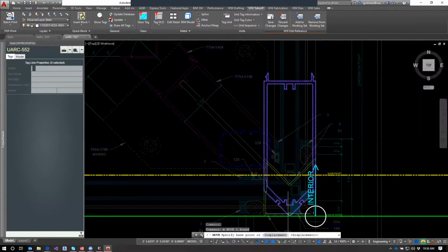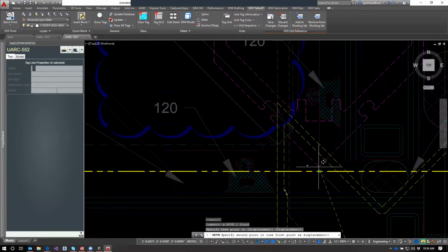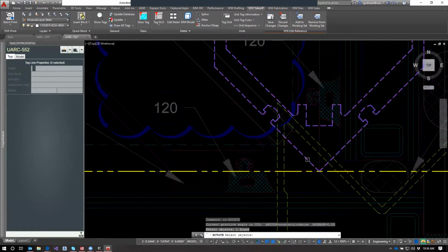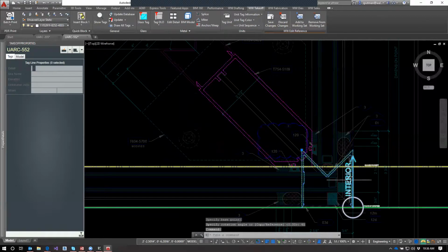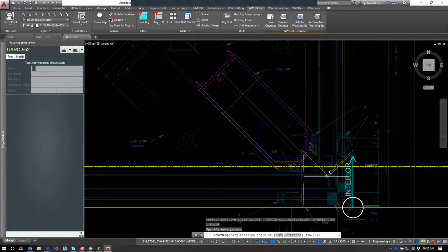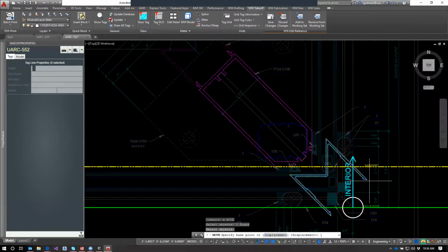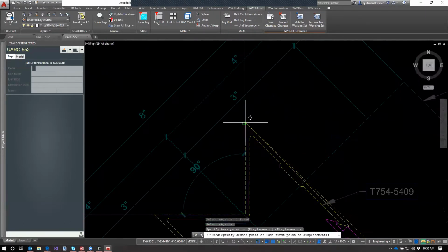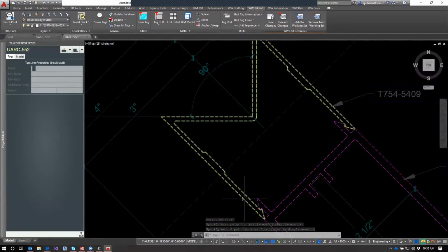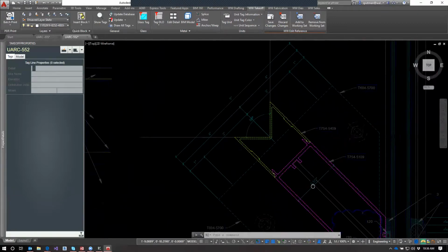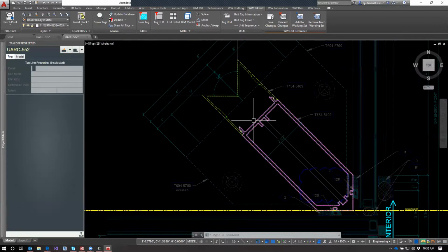All right, so again, just moving this thing around, putting it in the right place. This one I have to rotate 45 degrees. This one also rotate. I'm also looking to make sure that the part looks like the part in the detail, because if there's any issue there, then there could be something, you know, like the die is out of date, the shop drawings are out of date, I don't have the right die, it hasn't been finished yet, something like that.